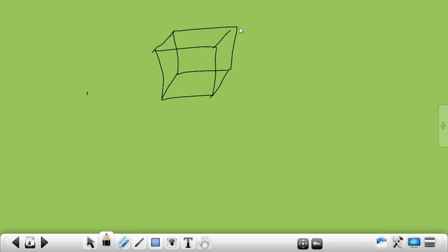This is the cube of length L, and here the cylindrical rod is present, whose length is given H and diameter is D. So we have to find the surface area of the rod, which is equal to pi D H, the outer surface area, plus the end and front side, which is equal to 2 times pi by 4 D square.